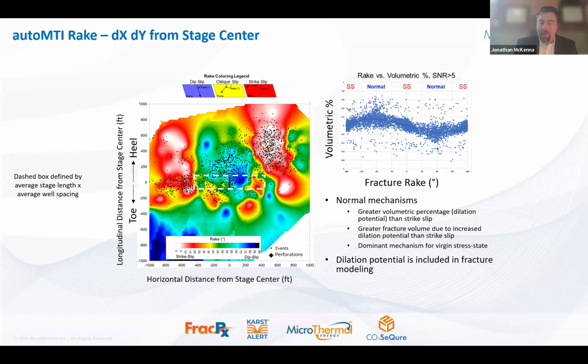areas where you have more of your proppant located. We've had the luxury of monitoring both the parent frac and the child frac. When we look at where those depleted events are located, they're simultaneously located in the areas that we initially modeled where our fluid would be located, and they're even more concentrated around the areas where the proppant is located.